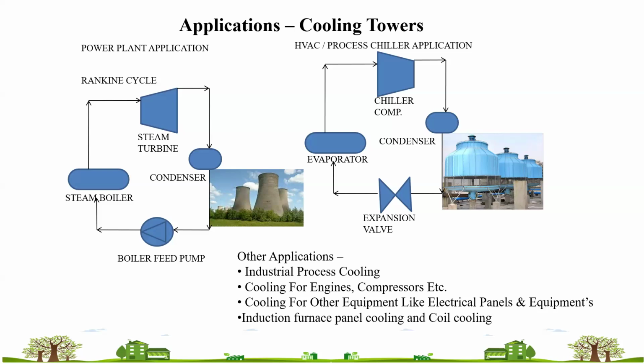And that is mandatory to provide a cooling tower to the induction furnace, because that induction coil cannot go beyond a certain temperature if you are not rejecting heat to the atmosphere. So that's how the application of cooling tower is important. Then other cooling applications: electrical panel cooling can be done with the help of these cooling towers. Electrical panel cooling is majorly done in induction furnace only. So these are some applications of cooling tower.